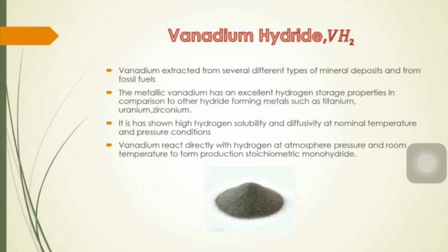Okay, next is vanadium hydride, VH2. Vanadium is extracted from several different types of mineral deposits and from fossil fuels. Metallic vanadium has excellent hydrogen storage properties in comparison to other hydride forming metals such as titanium, uranium, and zirconium. It has shown high hydrogen solubility and diffusivity at nominal temperature and pressure conditions. Vanadium reacts directly with hydrogen at atmospheric pressure and room temperature to form a stoichiometric monohydride.